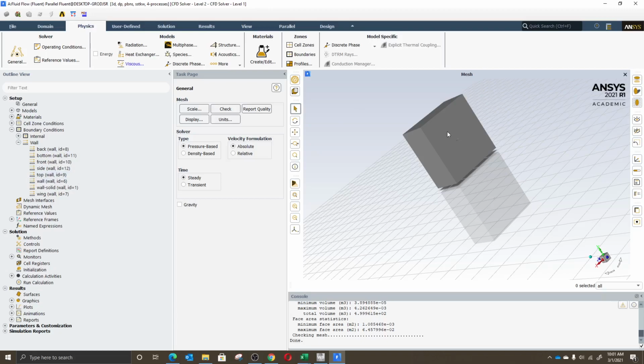and a wall boundary is essentially a boundary where you have a solid, right? Meaning that there's no fluid that can go inside it. The velocity of it, if you have a no slip condition, is going to be 0, okay? But the inlet and outlet velocity, fluid velocity, shouldn't be 0. So we want to change this.